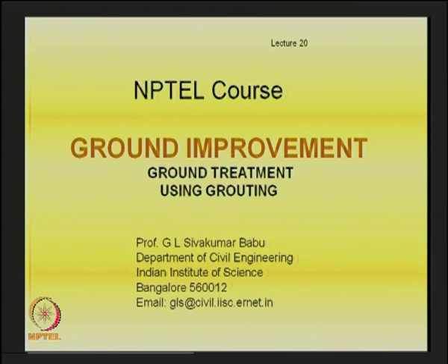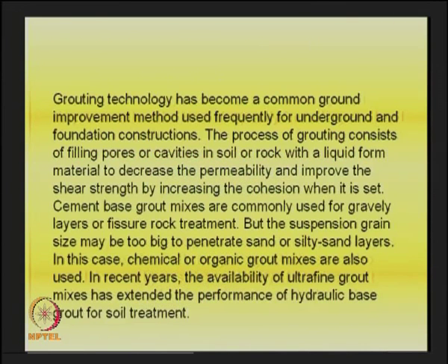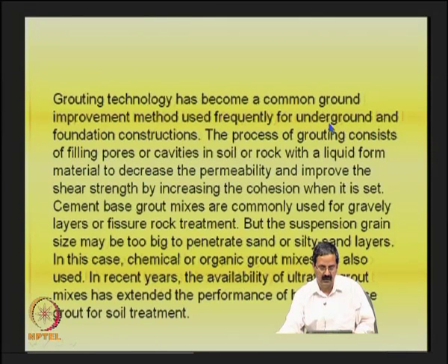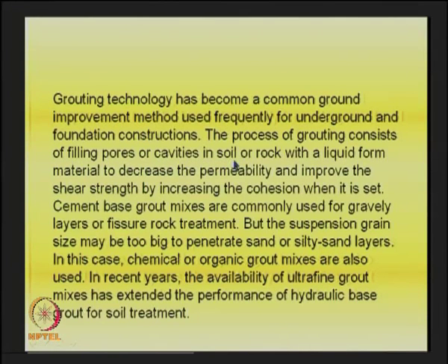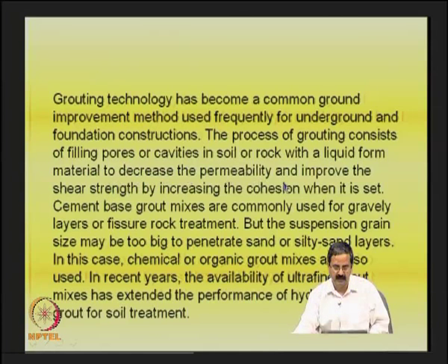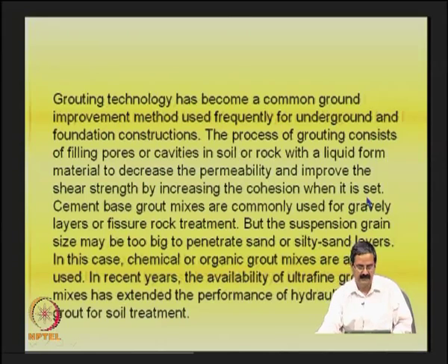We will be talking about using grouting as one of the ground improvement techniques in this lecture. This is one of the common ground improvement techniques. It has been used frequently for underground structures as well as foundation constructions. The process of grouting consists of filling the pores or the cavity in soil or rock with a liquid form material to decrease permeability and to improve the shear strength by increasing the cohesion when it is set.